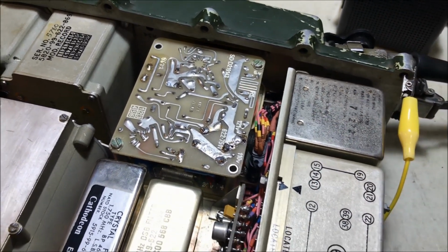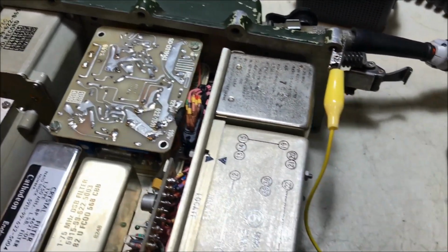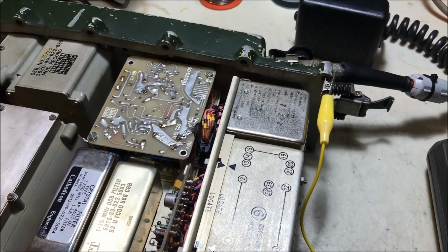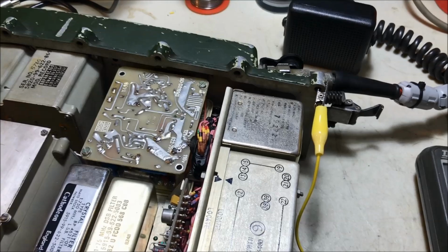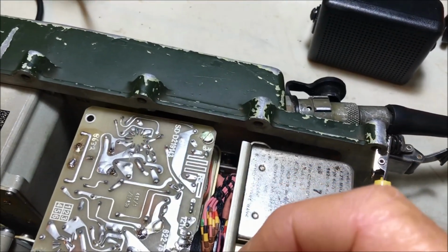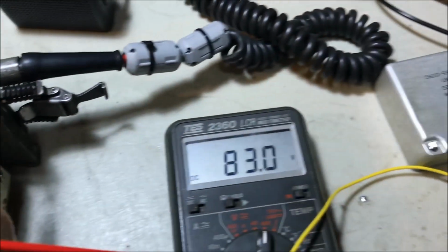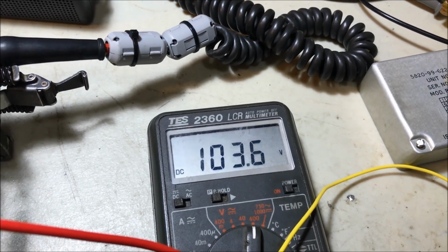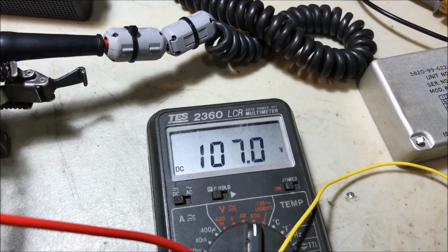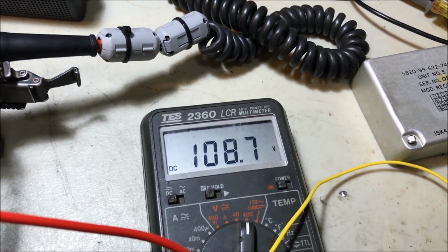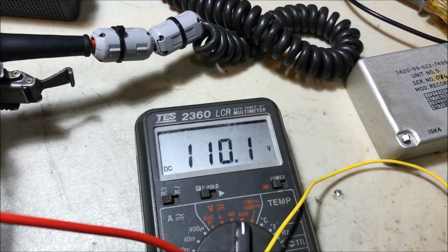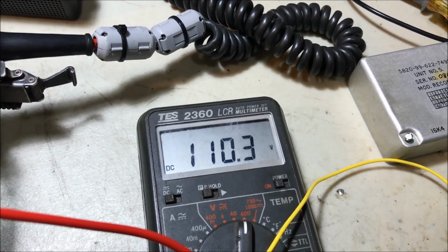So I'm going to turn the radio on, and we're going to watch the 110 build up. It's a bit hard to turn it on and have the meter on there at the same time, but I'll be as quick as I can. So now I'm putting it on there. Let's have a look at the voltage. See it building up there? Yep, that's the capacitors charging up. And that should come up to a nice little 110 volts. Okay, and the capacitors are charged up. There it is, sitting there nicely.